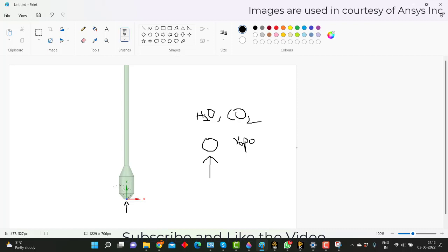A fluidized bed reactor is one where the force coming from the bottom is able to push the particles in the top direction, instead of the particles settling down at the bottom. So the gravity force, mg, is balanced by the upward lift force given by the air.